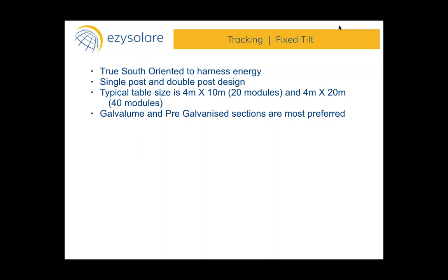Okay. So can I summarize that Galvalume is safe to use? Yeah, we can use it up to the highest strength, 550 MPa. Gurpreet, do you also believe Galvalume is safe to use? Galvalume is available from 0.8 to 1.2 mm in the market right now, and we strongly recommend using it in favor of optimization in fixed steel structures, but only in the purlin part of it. In purlins, we can use Galvalume.